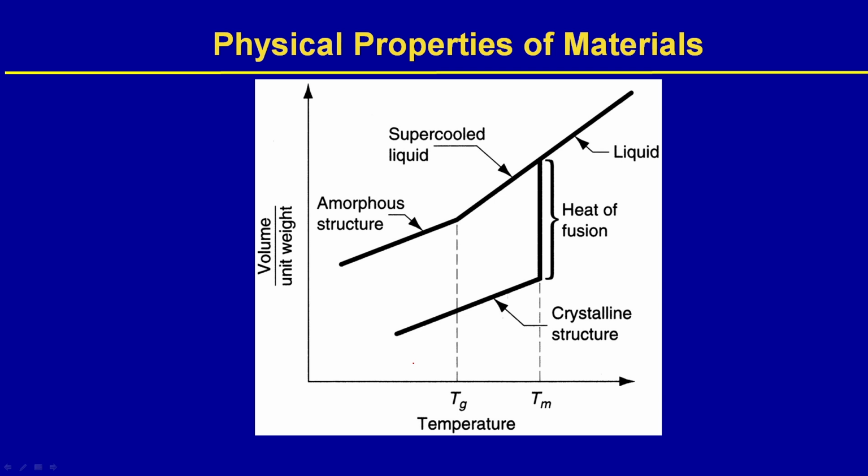As you know, if I have a liquid, let us take a metallic liquid, let us say pure copper, melt it down and then you are cooling it down. If I plot relative volume, volume per unit weight, as you cool down, this will vary like this. First it will drop and then there is a slope change. Why this slope change? Because if you cool rapidly to bypass formation of crystals or grains, then you will be able to freeze it like a glass or amorphous structure.